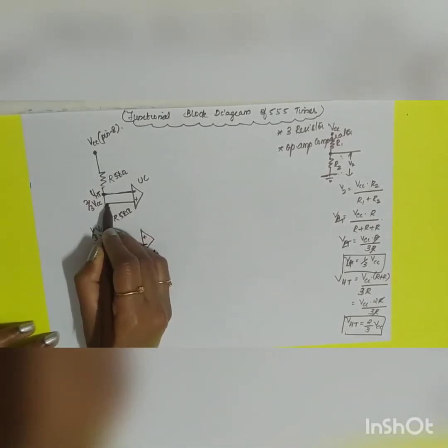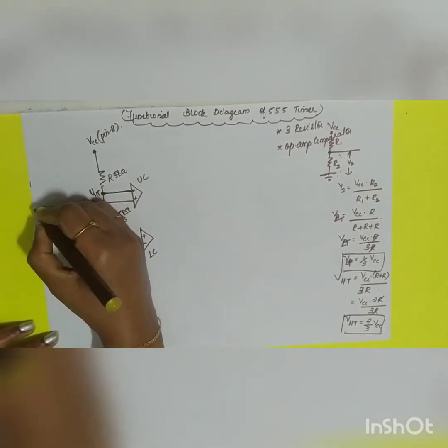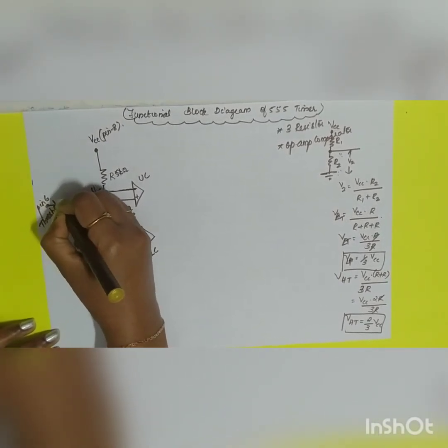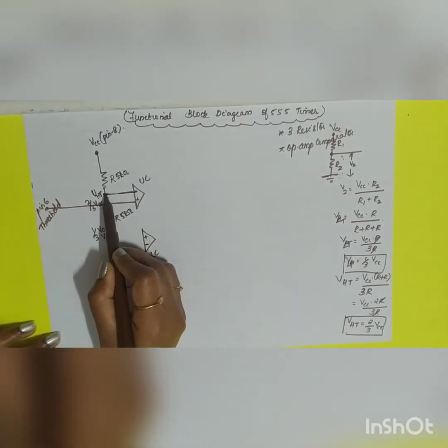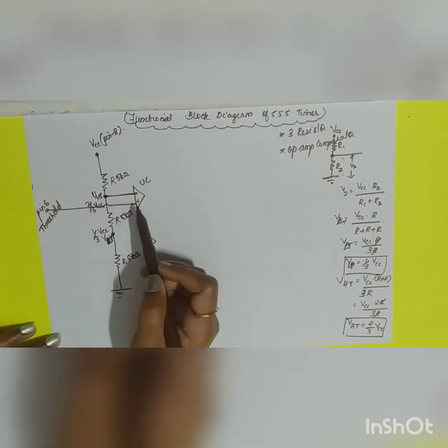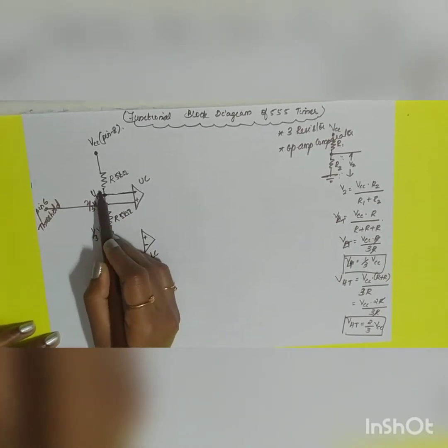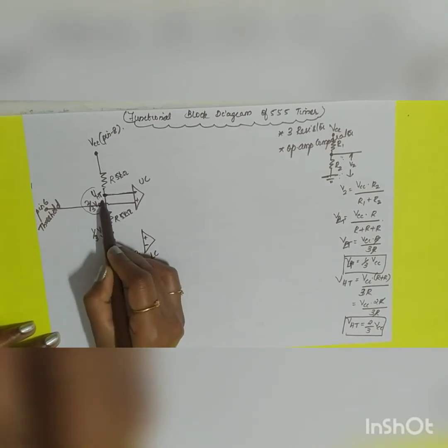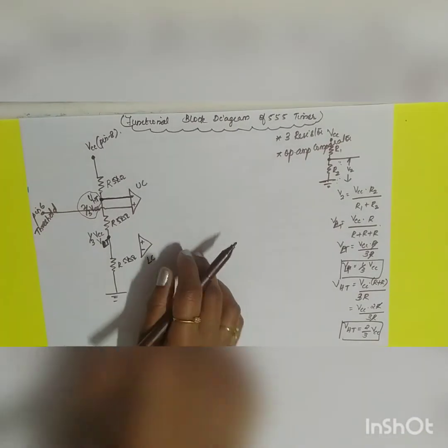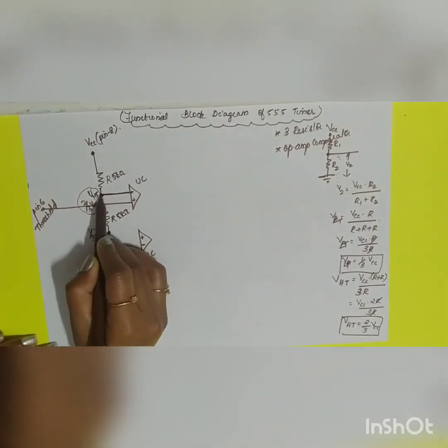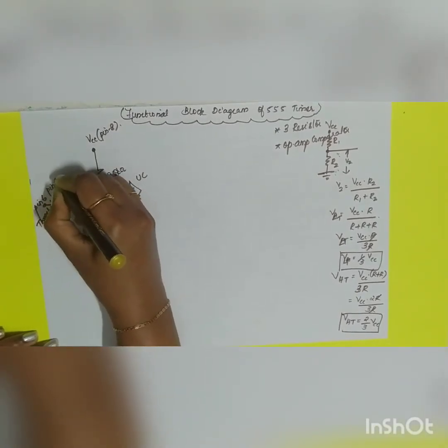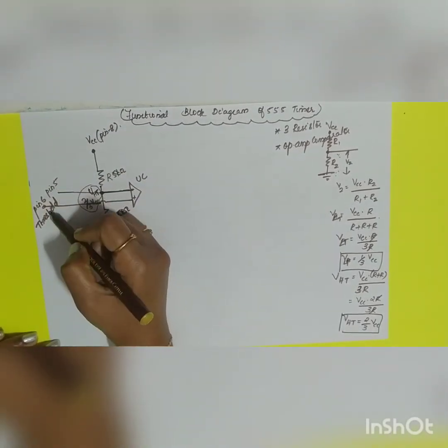So your non-inverting terminal will be going to your 6th pin, pin 6, which is nothing but equal to your threshold. Okay, so this VHT will be the reference for your upper comparator, one of the references, and the other input is going to be your what? So this is your 2 by 3 VCC VHT. Okay, don't confuse. The second input is going to be your threshold. Okay. So from the same VHT, you are going to take the connection that is your 5th pin, that is pin 5. So the upper comparator will be having your 5th and 6th pin connection.